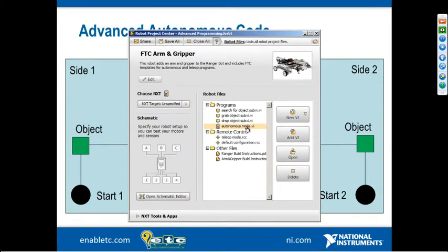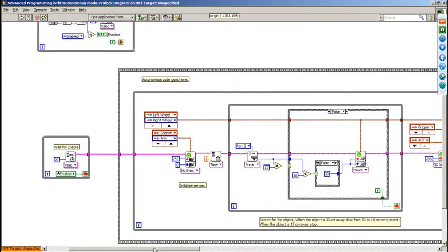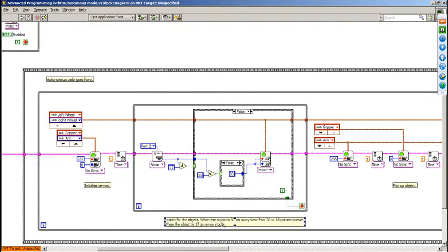We'll begin by opening up our autonomous code. Let's take a quick look at it to remind ourselves how it behaved. We have the always present wait for enable, which makes sure that nothing happens within our autonomous code until the field control system software tells us that we're okay to go. We have then the key autonomous code inside a loop. We start off by resetting our servo positions, having a short delay, and then driving forward while checking the ultrasonic detector to determine a relative speed.